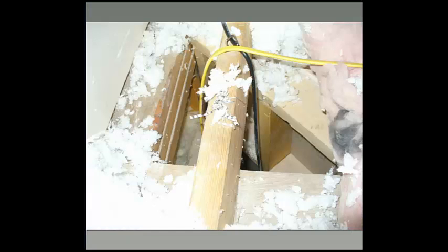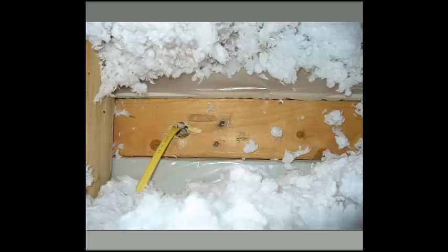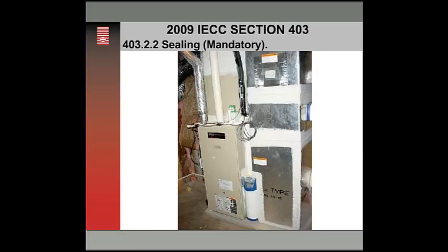But you can also go old school and rat around in the attic and find those bypasses just by digging around, uncovering big bypasses, and those would have to be sealed. That's a penetration in the envelope, electrical penetrations, top plate leakage, all of the likely suspects.